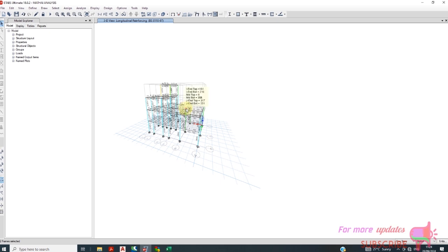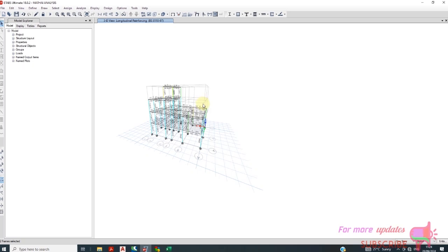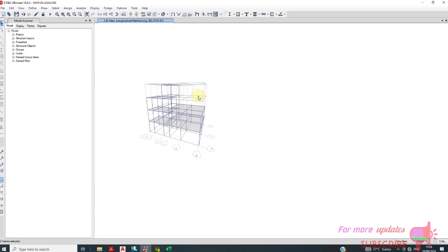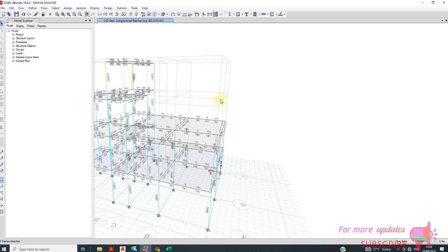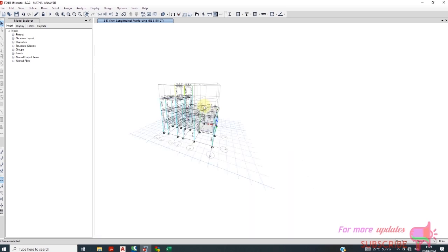But considering we don't have snow load in Kenya, and the wind load, this is not a high rise, I think the roof load is negligible. It's very minimal, and therefore I don't need to consider it in analysis. However, when I'm detailing, I should not forget that this column is going up to this roof level.